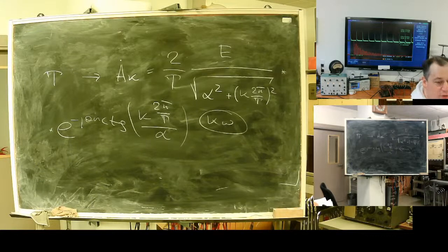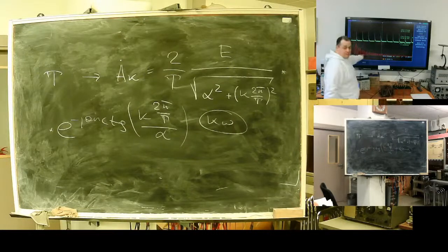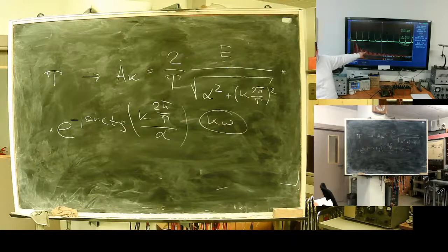See, I have a complex function. I'm representing it in polar coordinates, not Cartesian, to separate the absolute value. Why? My scope can perform a Fourier transformation, but it can display only values without angles.